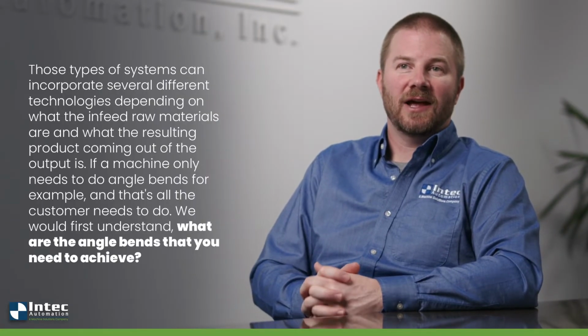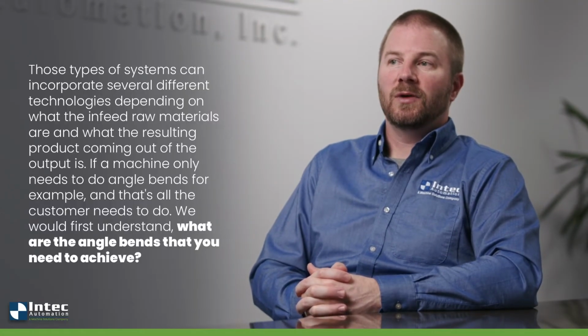If a machine only needs to do angle bends, for example, and that's all the customer needs to do, we would first understand, okay, what are the angle bends that you need to achieve? Are you going from 45 degrees to 60 degrees? Do you need a 0 to 90 degrees? Do you have any bends that go beyond 90 degrees? What gauge sizes are you trying to accomplish? What lengths are you trying to accomplish? What cycle time or production rates are you trying to accomplish?